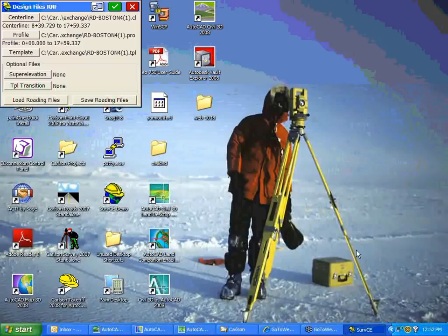Can the contour labels be set to not break the line and come in on a different layer and color than the contour? Actually, that's what I had. The contour labels actually did not break the line. There was just a wipeout under the label, or the line can just go right through it. I had the polyline contour continuous, with the wipeout there to hide the line. And of course, the text label and the contour polyline are on different layers, so you certainly can give them different colors.